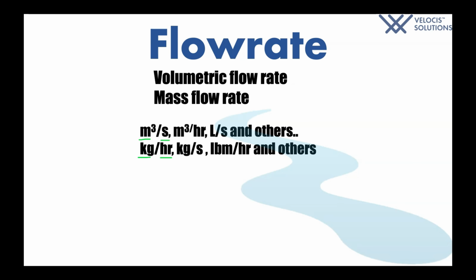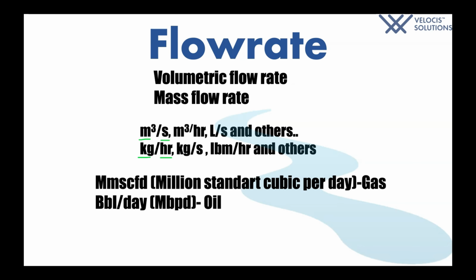Let me show you two very important units, especially for those who are working or planning to work in the oil and gas industry. We have MMSCFD and barrel per day. I hope that SCF chunk is familiar to you from the previous part. Actually, MMSCFD is an abbreviation for million standard cubic feet per day. Using million is a must here since we are talking about massive production capacities of oil and gas platforms, which cannot be expected to be a small number.